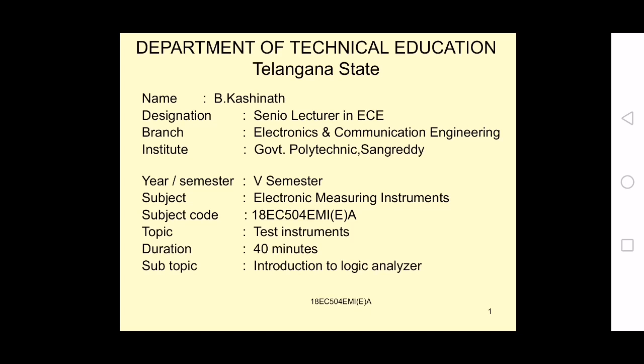The input frequency and your voltage tunable oscillator frequency beat together. When both frequencies beat, there will be a difference frequency. That frequency is the intermediate frequency, which is generated at exactly 100 kilohertz, which is amplified by the IF amplifier, then detected and amplified further, and applied to the vertical deflection amplifiers of the CRO.